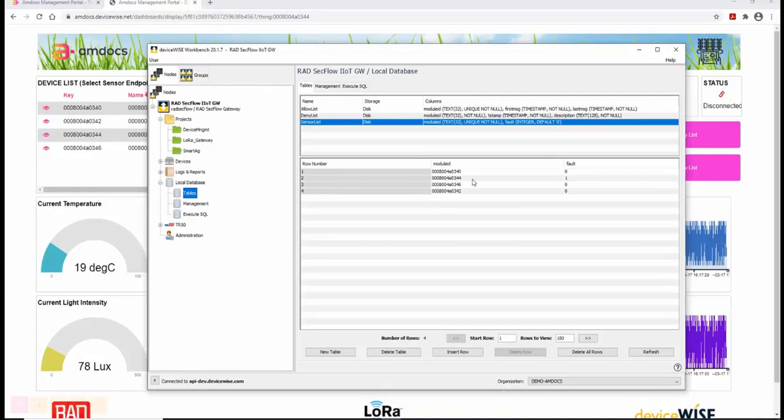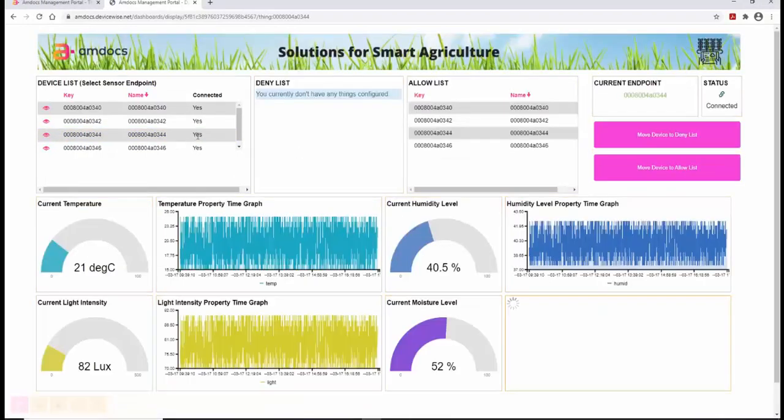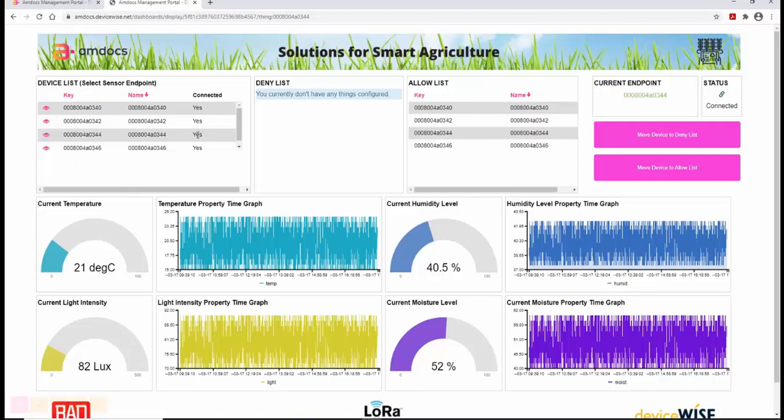To get this particular sensor back online, I'm actually going to take advantage of the gateway here, and we'll change that state back to get it out of a fault state, and change that state here at the edge. And so what just happened at the edge is we communicated back downstream to that particular edge sensor, the 344 edge sensor, to basically perform a reset. And as a result of the sensor performing the reset, you'll see this just flashed yellow. If we refresh our screen, you'll see that now the sensor is back online. It's in an active state. It's cleared from a fault state.